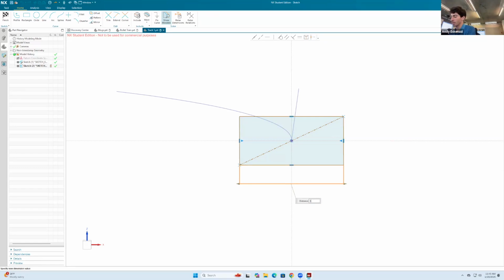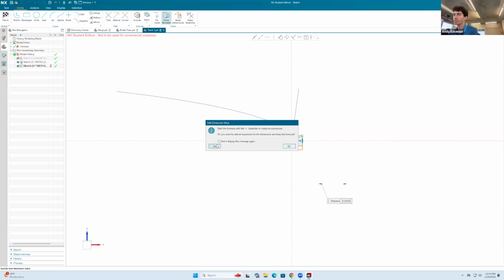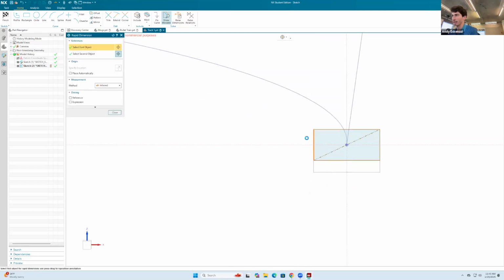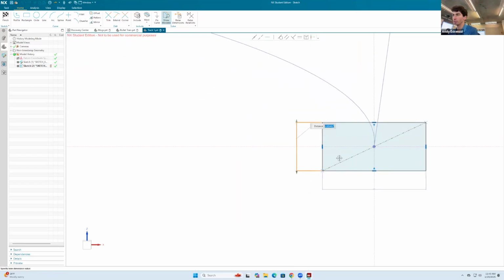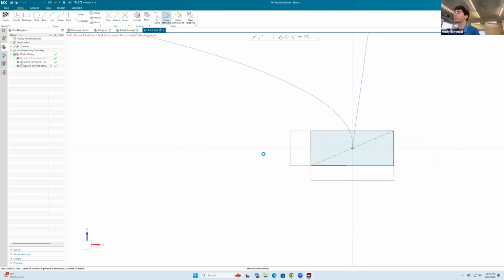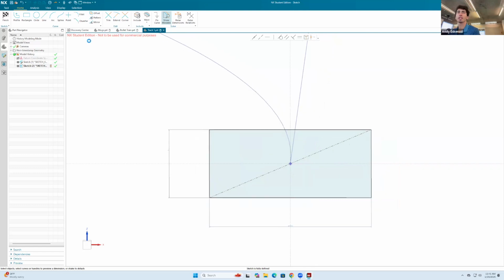So I'll make this 8 plus 4 plus maybe 2 mm more. I'll say that's okay. Yes. And I say that I want the overall height of this to be 6. That could work there. That's fine. And I'm gonna design 2 little rectangles like this.